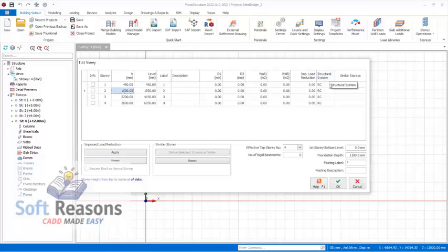All right, then the structural system at the foundation level, which is from story 1, is going to be ROC. Then from story 2 to story 4 is going to be steel, just like this. So the depth of the foundations in your calculations, you have to put the 450 millimeters as part of the foundation depth. Right here, 1100 millimeters is the default foundation depth for that structure. If you add this 1100 plus 450, you'll have 1550 as the foundation depth for that structure. For now, we will go by this. Click on the OK option.